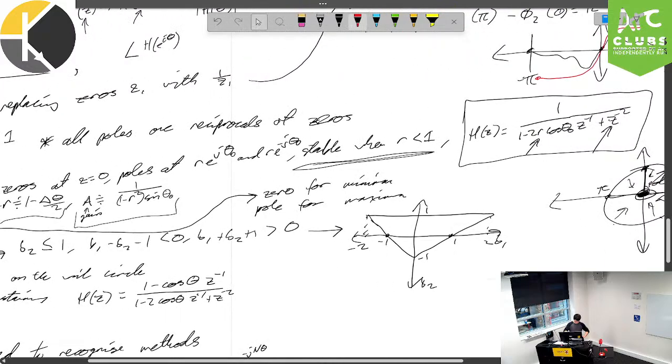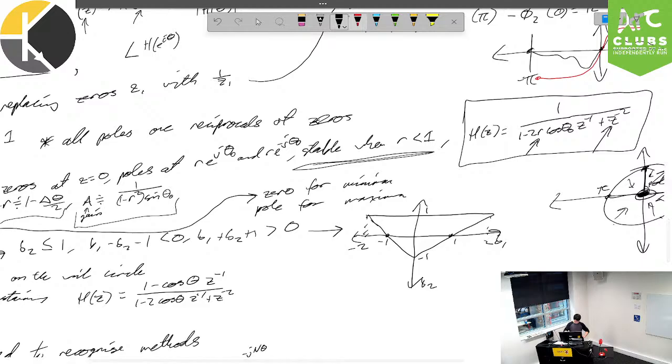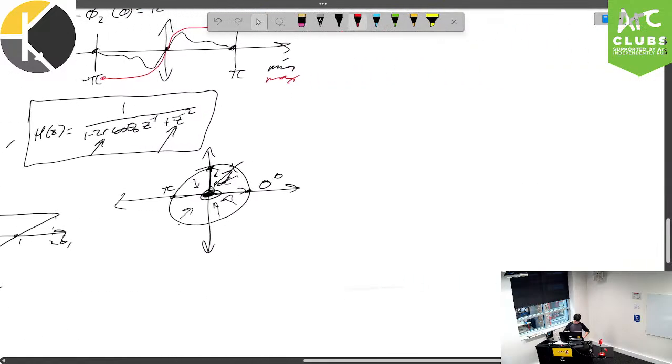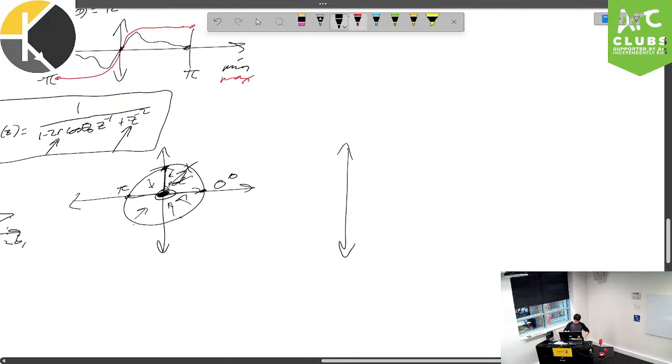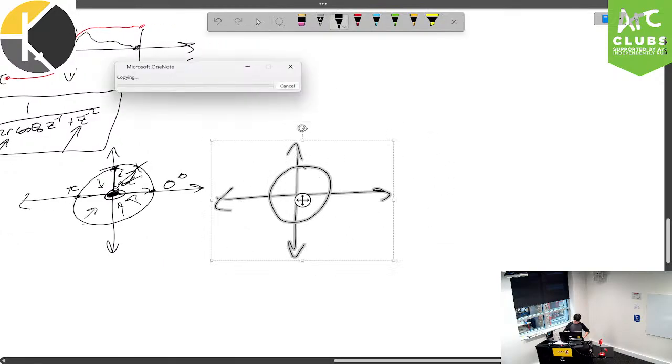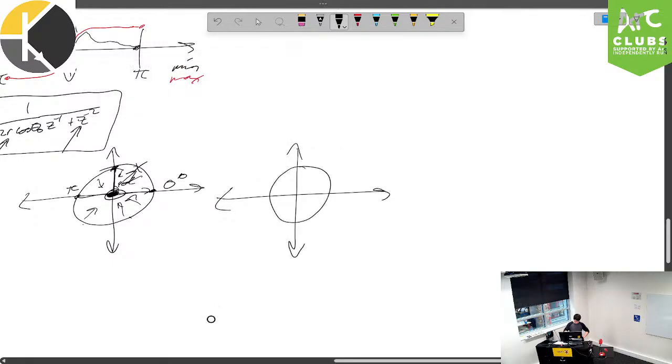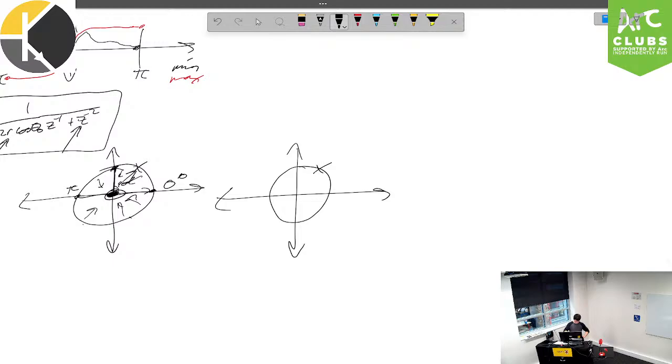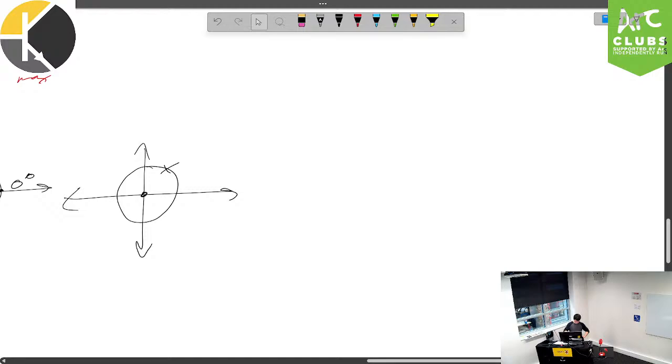And so we place zeros for minima within certain frequency areas, and then poles for maxima within certain frequency areas. And the greatest way to think of this, I'll just draw another circle. We're going to be drawing quite a few circles today. In fact, to save a little bit of time, I'm going to copy it for later. So, we have our circle here. If we place a pole right on the unit circle, and maybe a 0 in the center, what we'll observe within our frequency response